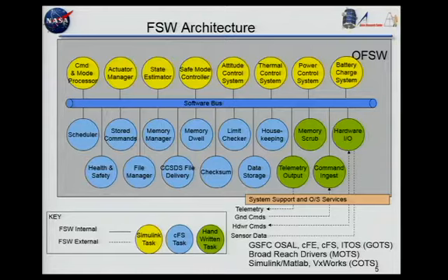We have a Simulink interface layer that provides the proper CFE wrappers for communicating on the software bus, and also gives us table services. So these applications are controlled just like any of the other CFS applications on the bus. The blue bubbles here are the standard CFS applications that we used, and the green bubbles were the hand-developed items on the spacecraft. And of these, probably most of the hand-developed software was in the hardware I/O, talking to all of our hardware systems. And Doug Foreman will be talking about that on the final day.